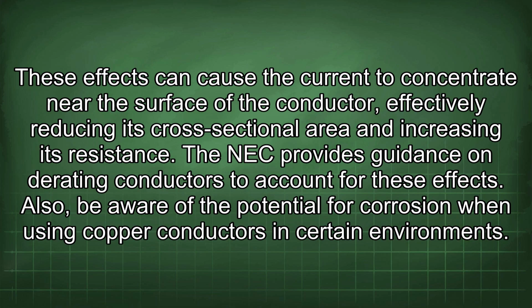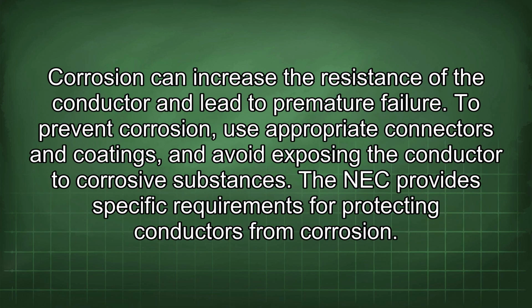Also, be aware of the potential for corrosion when using copper conductors in certain environments. Corrosion can increase the resistance of the conductor and lead to premature failure. To prevent corrosion, use appropriate connectors and coatings and avoid exposing the conductor to corrosive substances. The NEC provides specific requirements for protecting conductors from corrosion.